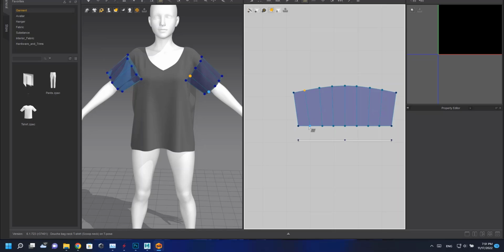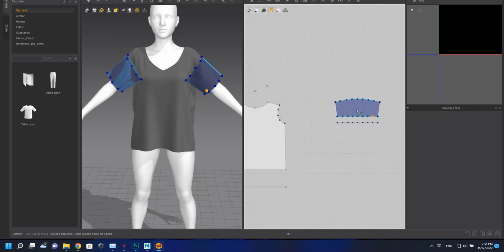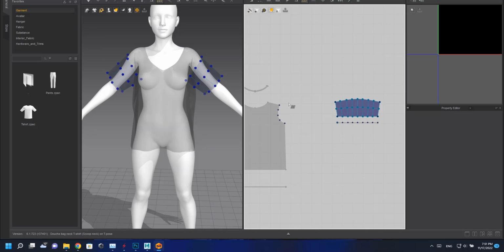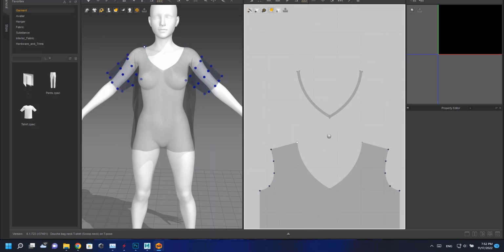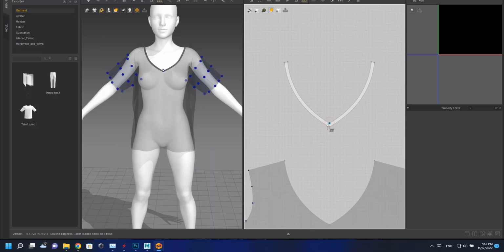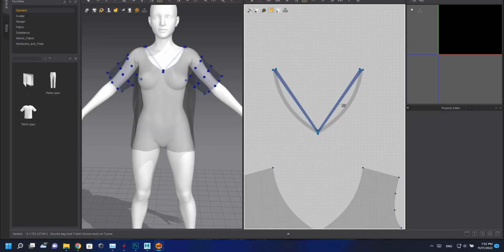The larger the clusters, the more UV space they take up and the higher the quality of the material. Try to adjust the clusters so that they are as large as possible in UV. If it is necessary to have several clusters of higher quality separately, we should increase the size of these clusters, and it is better to choose parts that do not need high quality and reduce the size of their clusters.